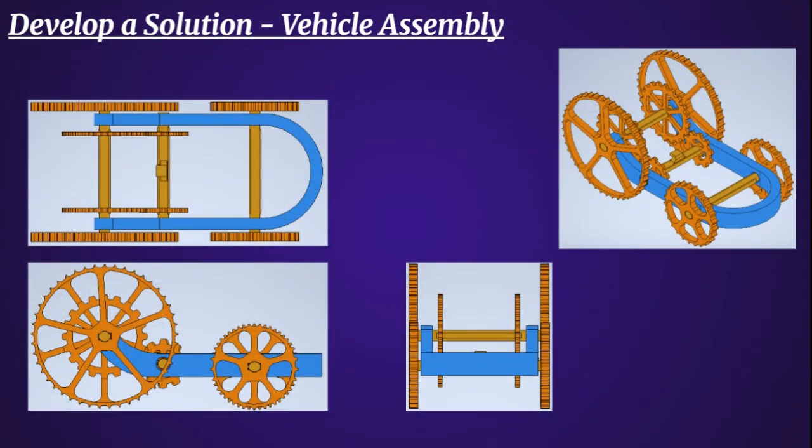This is what my vehicle design looks like, and is planned to look like once assembled in Inventor. I used joints to assemble the vehicle together. For some reason, I kept getting error messages when I tried to use constraints. So my Inventor assembly does not move at all like it's supposed to.